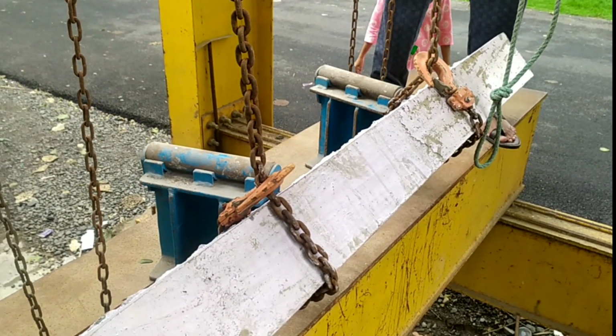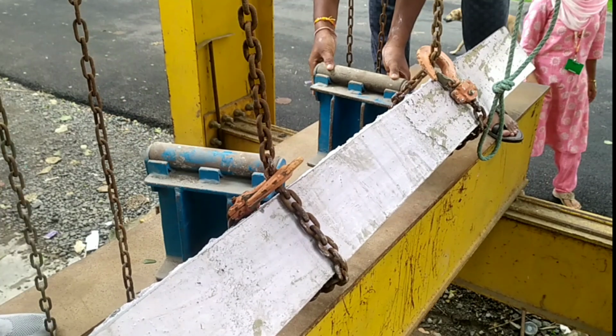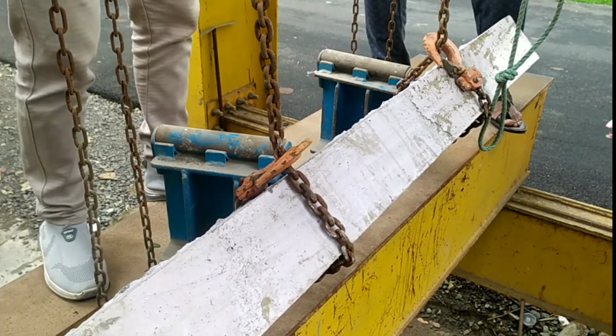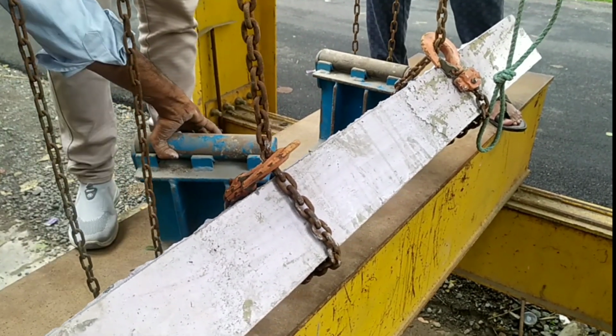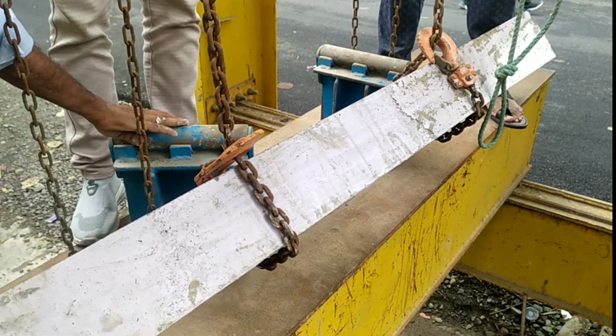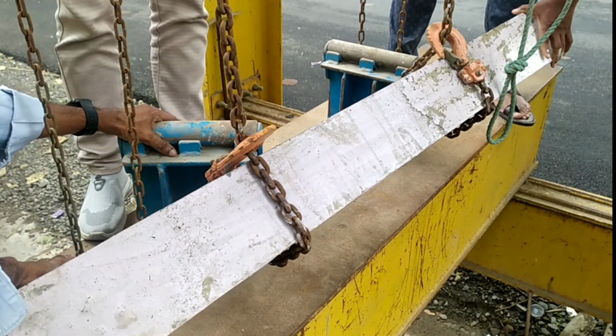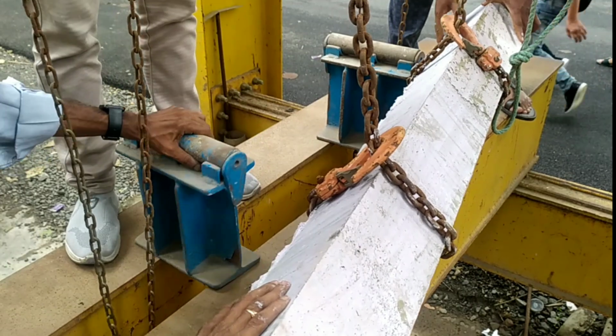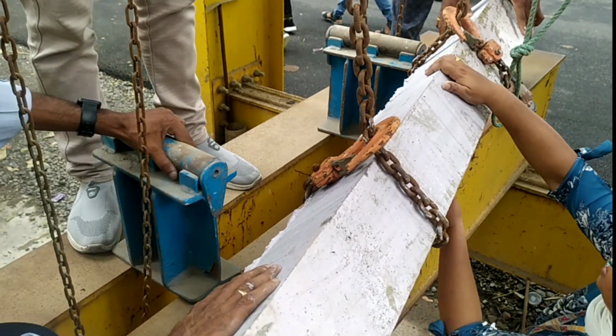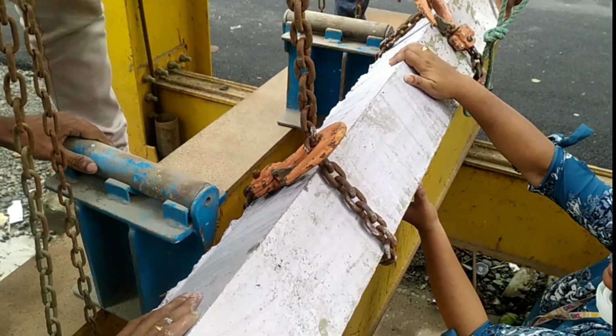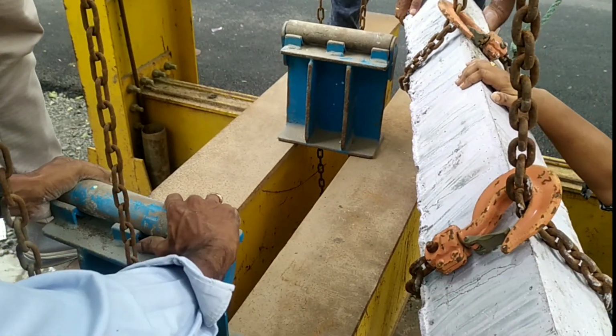The test was carried out in the structural loading frame. A hydraulic loading system was adopted as the loading equipment. The maximum thrust load is going to be applied on this beam. The stiffness of the supporting structure of the testing beam must be large enough to reduce the measurement error.